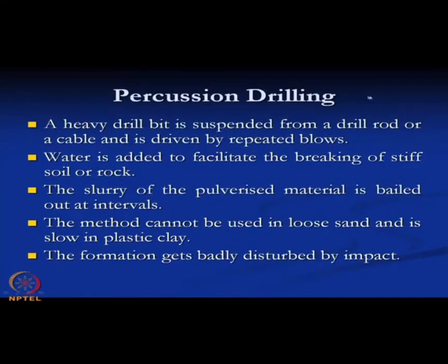Next one, percussion drilling. A heavy drill bit suspended from the drill rod or a cable is driven into the soil by repeated blows. Water is added to facilitate the breaking of hard rock or soil. The slurry of pulverized material is removed at certain intervals. The method cannot be used for loose sand and it is slow in plastic clay. The formation gets badly disturbed by impact.